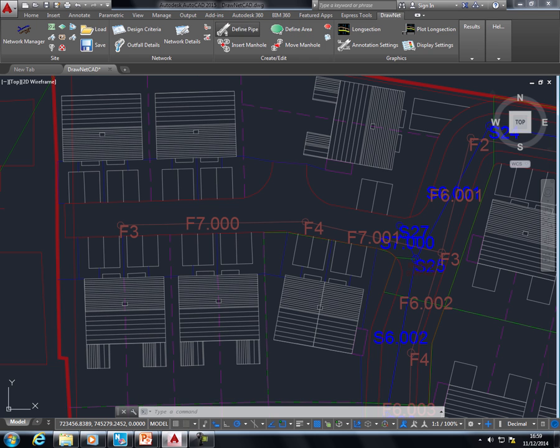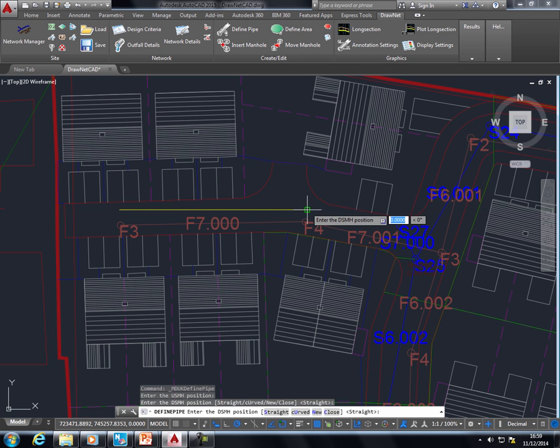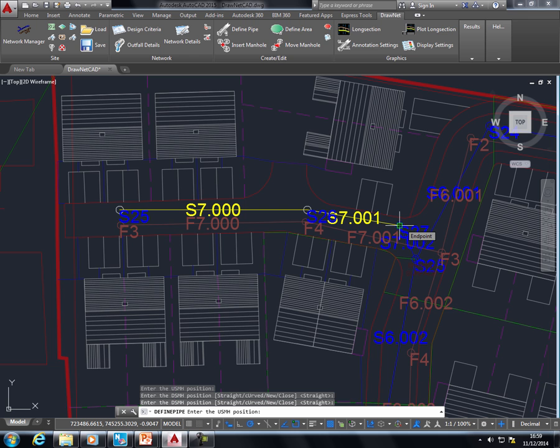So I simply click on define pipe, and then I can click on the upstream manhole position. You may have a tracing of these provided by the engineer, and then give this work to the AutoCAD technician to then click on the upstream end, click on the manhole downstream, and then click on connecting into the existing network, the network that I've designed a little earlier on. And we've now reinstalled those 2 pipes that were deleted. Within AutoCAD, if I just escape from that command, I can click on this manhole. If I wanted to move that manhole across, that would be easy enough to do.